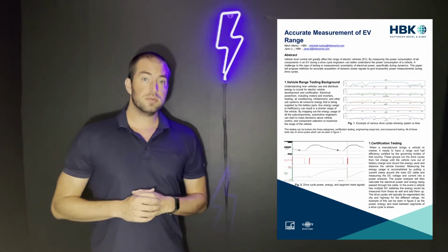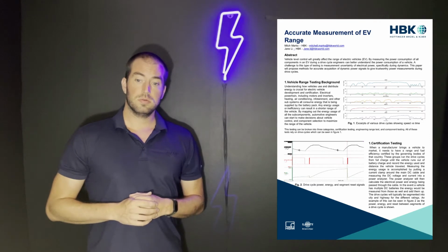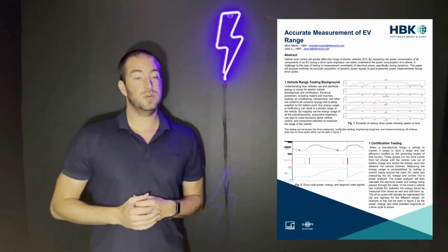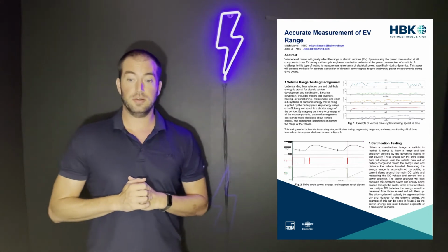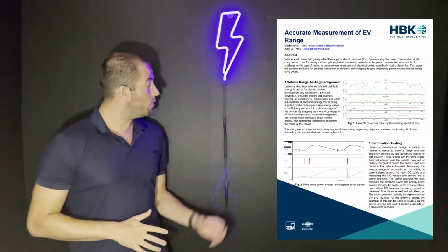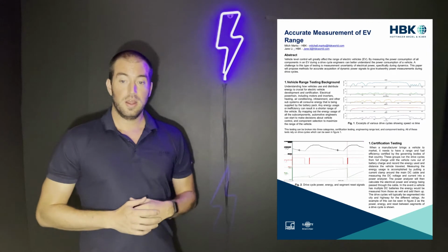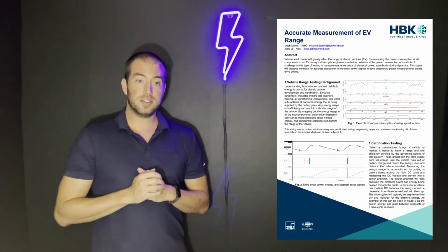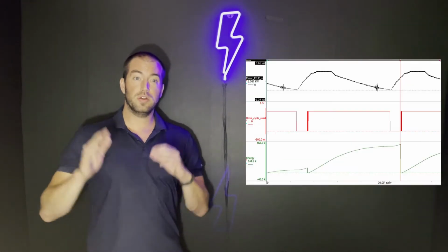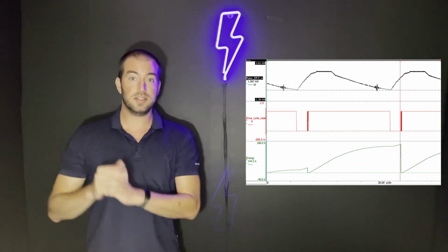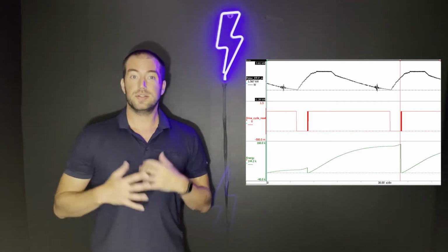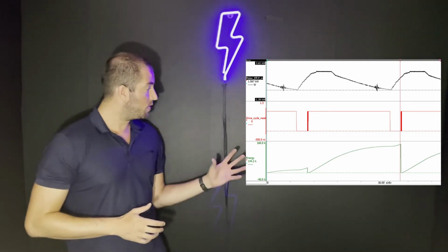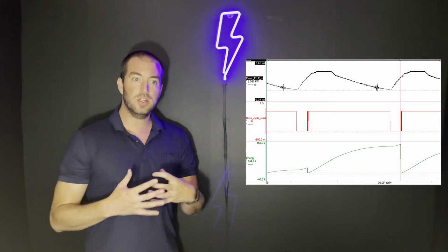And we're going to do this over the exact same situations that we do the certification test. So we're going to run through the different city and highway drive cycles, but then we're also going to measure the power. We're going to look at when we reset through each scenario, so we can look at what the highway mileage is and what the city mileage is. And we're going to calculate energy through each one of these segments. So this is really cool. We can actually understand what the energy consumption for each component for each segment is.